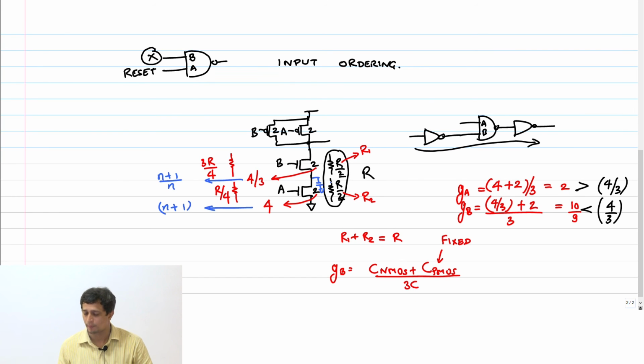So what happens to the parasitic delay? So again, yes, that will change. You've got to recalculate all that a little bit. And in fact, even here, you're right that you have to look at the layout now. However, it is still true that parasitic delay does not change if I upsize this gate. That still remains true. Therefore, my gate sizing algorithm still doesn't care about it. It's a constant number. You have to calculate a new number. Forget about it. That's all. You have to do Elmore delay again to get this number right.